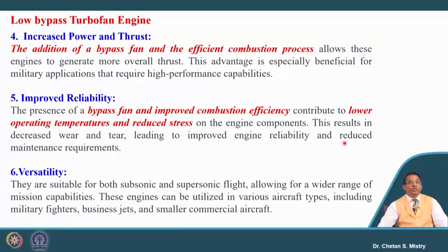The low bypass ratio engine has enhanced power as well as thrust, because we have the additional bypass fan and an efficient combustion process. That is what leads to the increased application of such engines for military purposes, where we are looking for high performance capabilities. At the same time, because of the bypass fan and improved combustion efficiency with lower operating